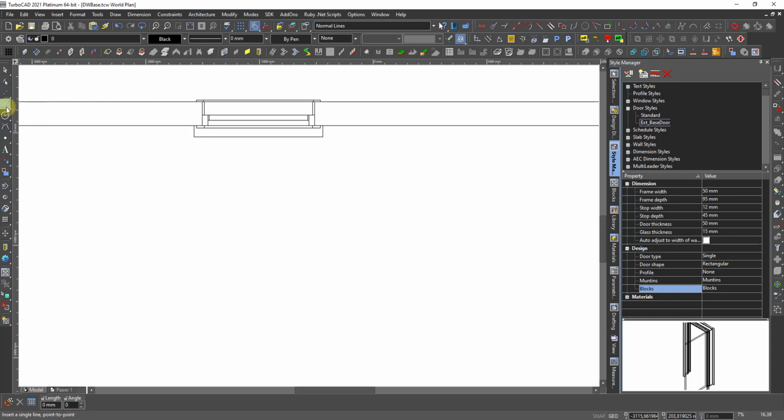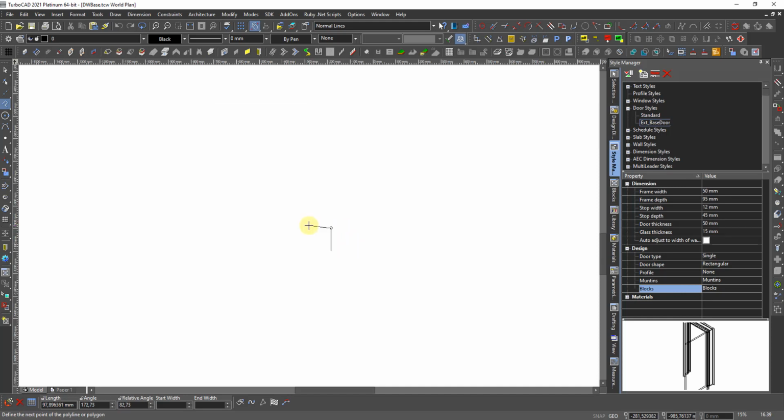Escape. I want to have a polyline. The length should be 100. The angle should be 90. And then I should have a little bit up here. To say 25. It's not important what it is. And then the angle can be 178. 178. Yeah, that's okay.